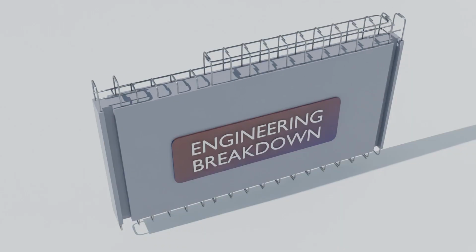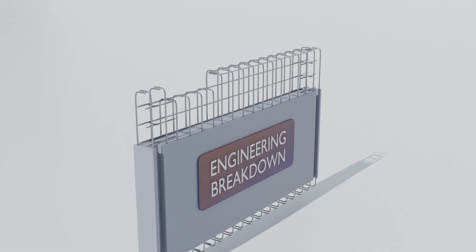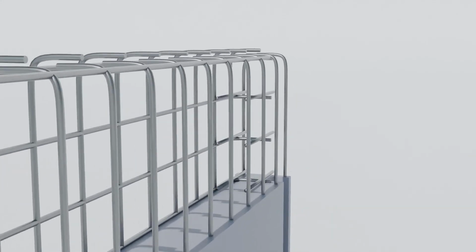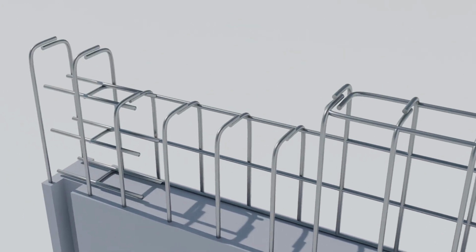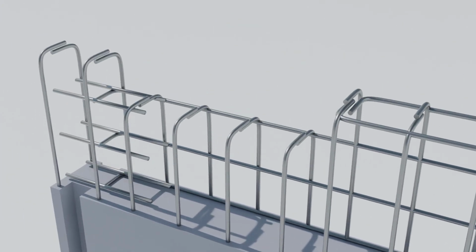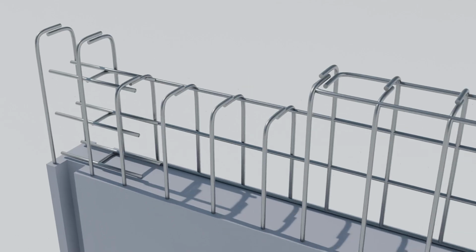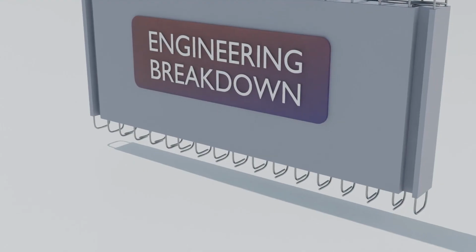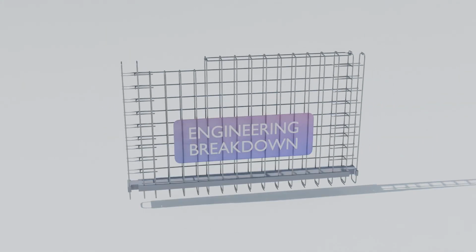Let's take a closer look at pier reinforcement. The reinforcement is arranged in a particular way in the pier, conforming to its shape as shown. The bars are curtailed or given 90-degree hooks at particular areas to fit the geometry. The vertical bars here are lowered for the slab to rest. However, they could be raised if we wanted the slab to be integrated into the wall itself. The bottom bars were used as dowels into the bottom slab for connection. Let's move to the next reinforcement.